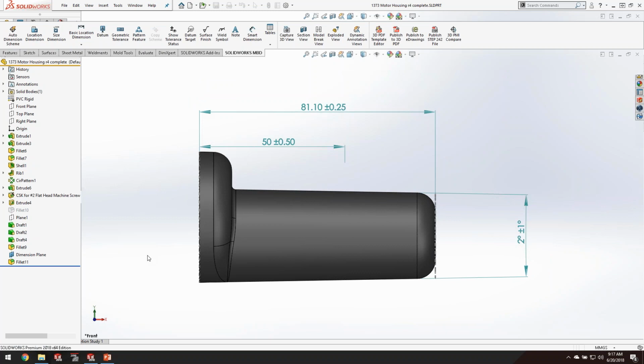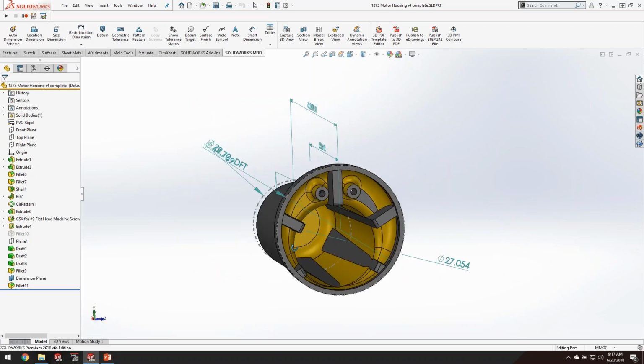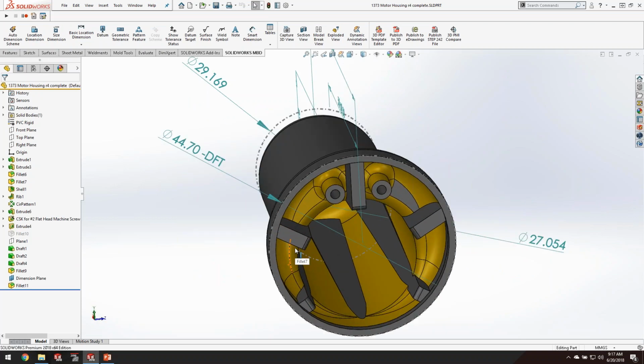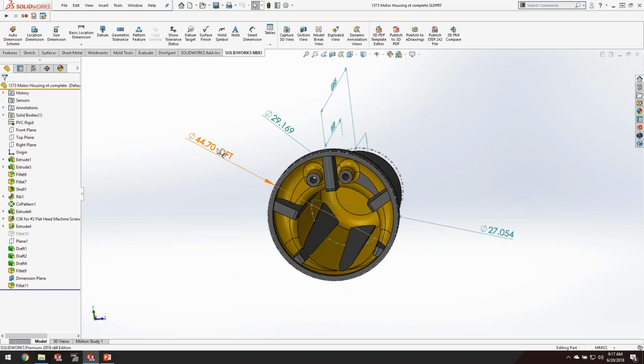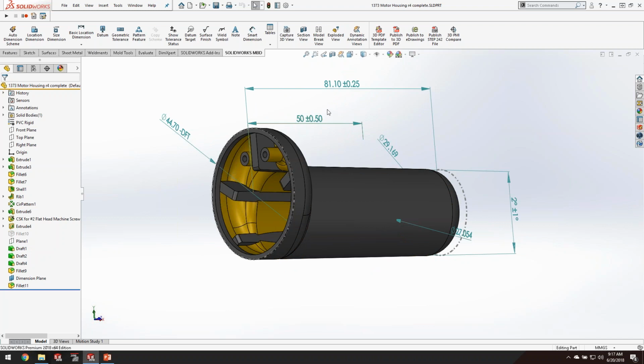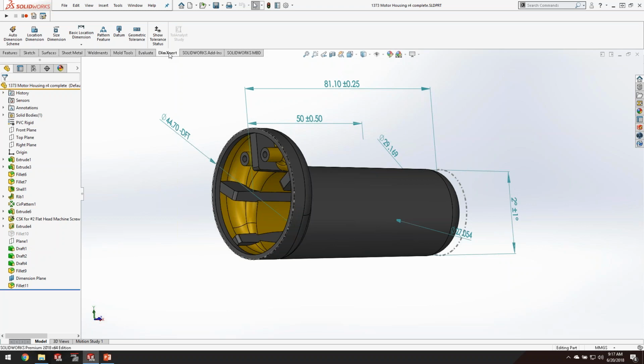So we all know that you can take a 3D CAD model and build it inside of SolidWorks. But how many of us are familiar with the ability of adding dimensions, these outside dimensions, onto the system that we can then add tolerance values to? So this is actually something that's been inside of SolidWorks for quite a while. It's been known as DimXpert. So there's a tab inside of all SolidWorks users. You have the ability of enabling this or disabling this.